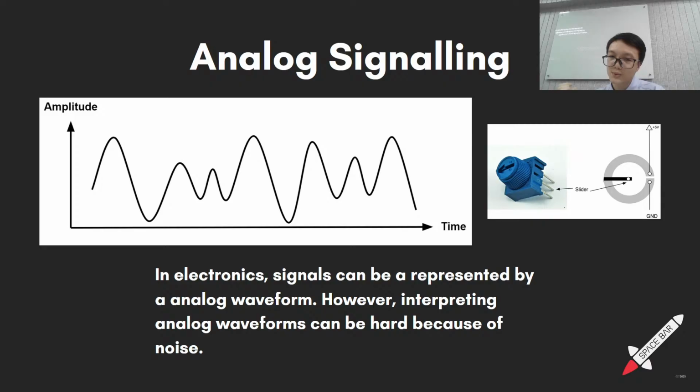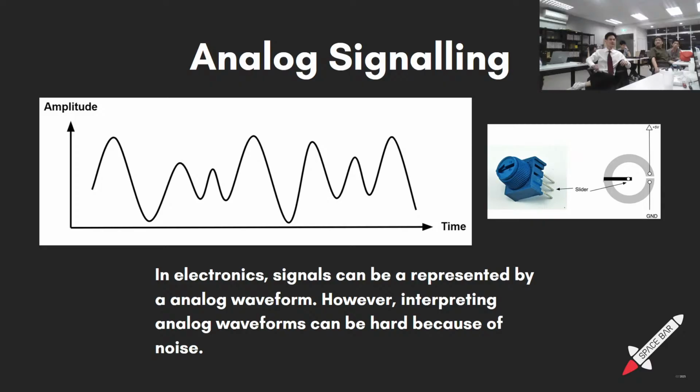Noise is basically like, remember how we had capacitive and inductive coupling? You can have 50 and 60 hertz power in the walls, and random radiated power from who knows where, and all of this can induce voltages in your circuit and create random currents. So even if you apply an exact 3 volts to this line, that line can fluctuate a little bit or a lot depending on your environment. This is electrical noise, and it is a problem for all electrical circuits. RF, everything just affects the circuit, and we don't like that.